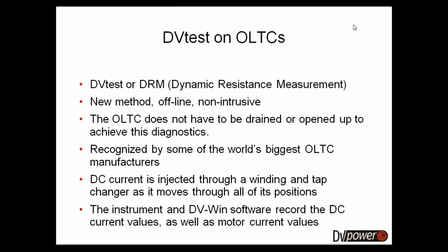First question is, what is DVTest? DVTest or dynamic resistance measurement is a method of testing on-load tap changers or OLTCs, which determines their condition without the need to open up the tap changer compartment and without the need to actually go into the tap changer pieces and internal construction.